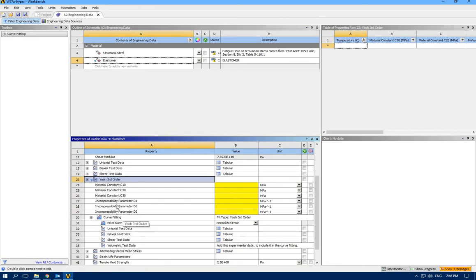This model comes with 6 coefficients which we need to calculate, and if you have these coefficients, the model would be complete, and ANSYS understands the formula extracted from these numbers. But because we have some experimental data, we are going to fit some curves to those experimental data and ask ANSYS to generate these 6 parameters out of those fitted curves.